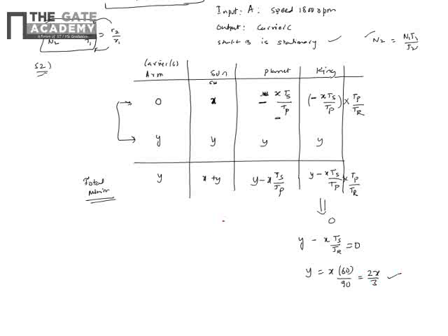That is one condition. Now the speed of A, the input shaft, is 1800, so x plus y is 1800 revolutions per minute clockwise. These are two equations, and the variables are x and y, so I can just eliminate and solve to find x and y. So x plus 2x by 3 is 1800, and so x will be 3 by 5 times 1800.